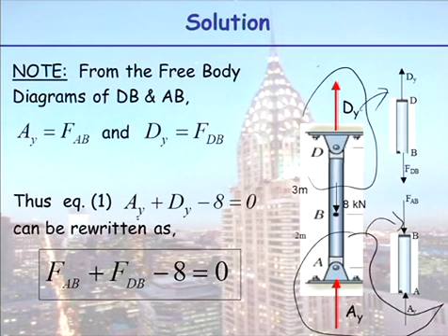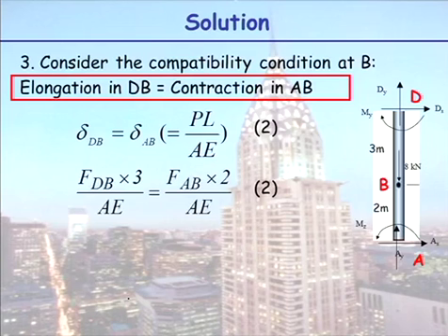And so our equation, even though we started off looking at it in terms of reactions, can be written in terms of internal member forces. Whether you choose to write it in terms of reaction or internal member forces is up to you, as long as you know they are one and the same, they have the same value. Okay, so we have one equation, and now we need to look at our compatibility.